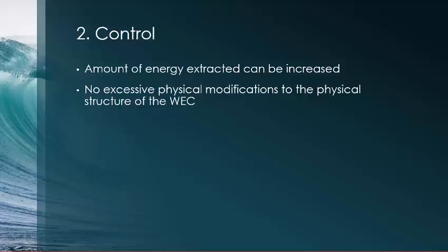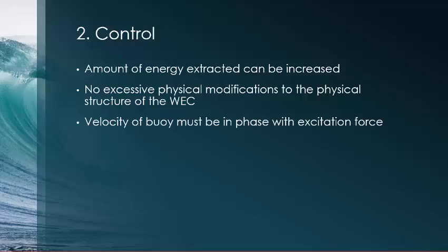For point absorbers, the condition for maximum power extraction is that the velocity of the buoy must be in phase with the excitation force. Excitation force here is the wave excitation force, which is the force exerted on the buoy by the incident wave. We can put it in another way and say that for maximum power extraction, optimum oscillation must be achieved, and this is achieved only when the buoy is in resonance with the incident wave.